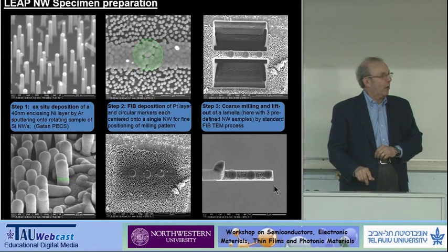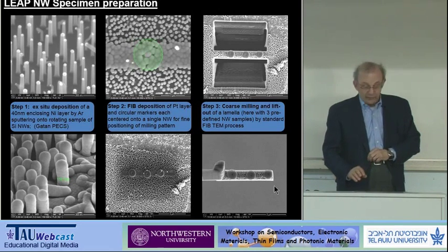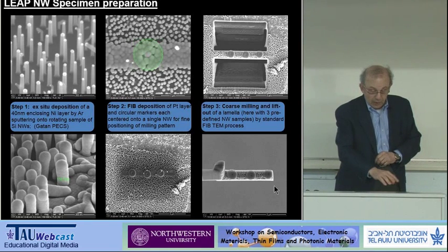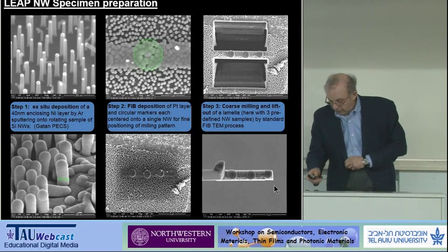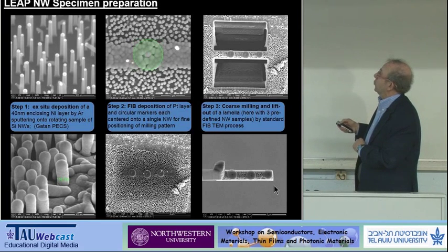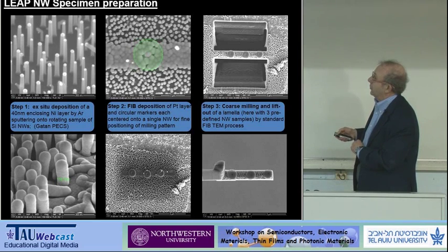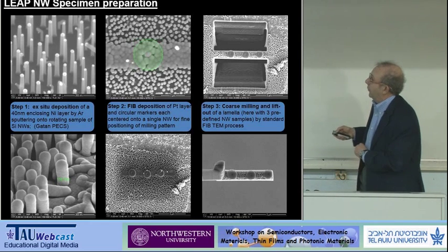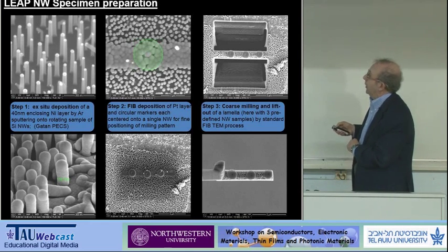Here are these nanowires that were grown with aluminum as a catalyst, and they had a very high number density. You can see one over here, and then you isolate a few, so you deposit platinum. This is done ex situ, all of this. And then you isolate some like this in this region here, and then you want to analyze these 3, so you cut out